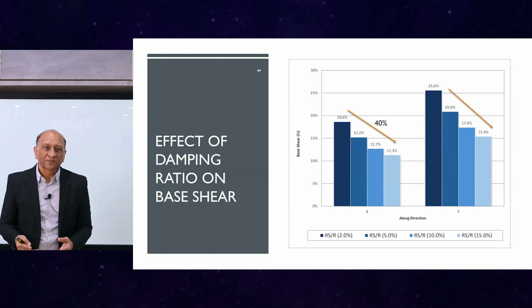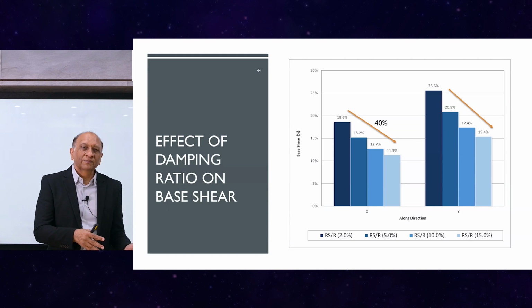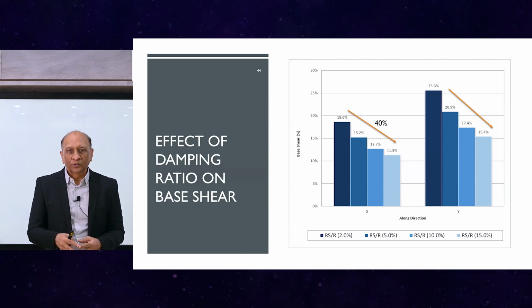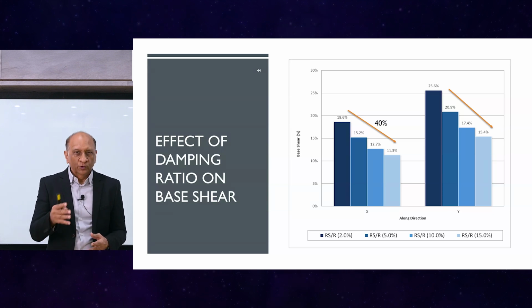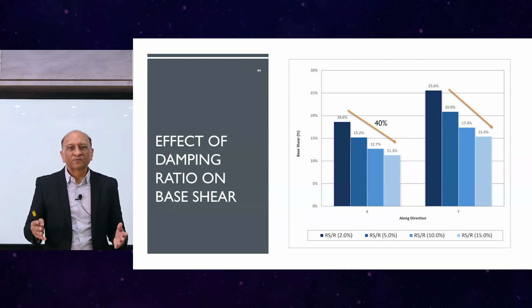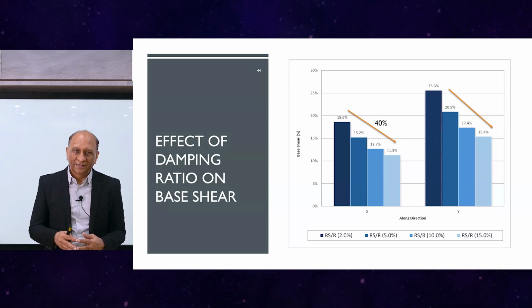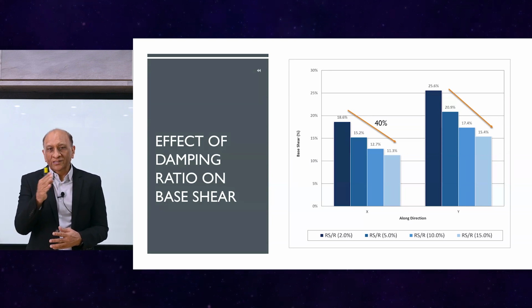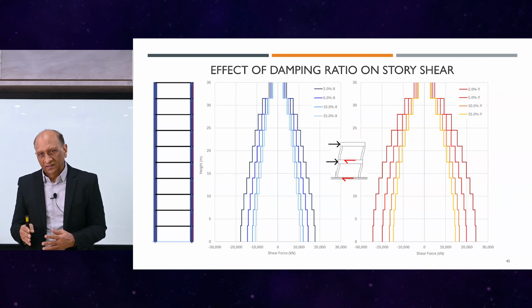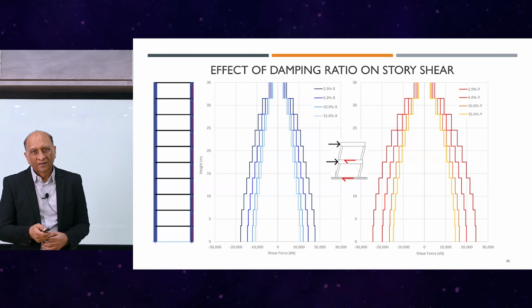So it's not just the building natural period, but also we need to see where the building is located and what the response spectrum looks like for that region to see which part is critical, which is not. And if I plotted the change in the stiffness and the change of damping for a 10-story building in Bangkok, you will see no difference. In fact, you will see a slight increase on the contrary, rather than a reduction. But in the range from 20 to 30 stories, there's a significant drop, and then it flattens again. So that's the important observation for both.